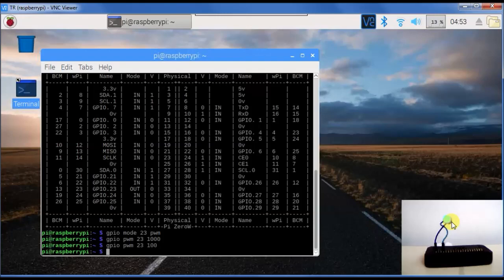The hardware PWM of GPIO 12 and 13 can generate a very stable PWM signal, but can only be accessed from the command line with this WiringPi tool. Node-RED only provides software PWM, which cannot be used for dimming because of glitches caused by the interrupts of the operating system. These glitches cause visible flashing of your light.